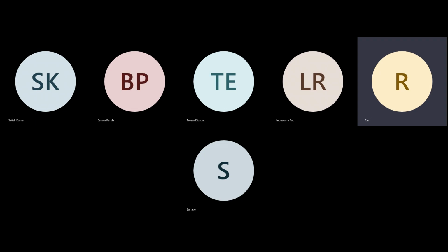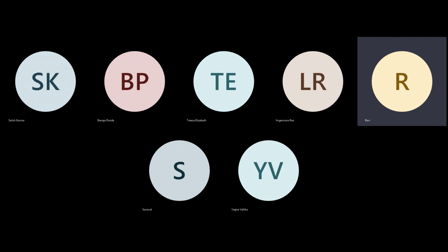You cannot abut all 16 macros together. You will place them in certain rows, or maybe 4 or 5 together. First, how many macros can be abutted without logic space? You have to understand that a macro pin can drive maybe 100 micron or 200 micron. Beyond that, the load capacitance on that pin will be higher.